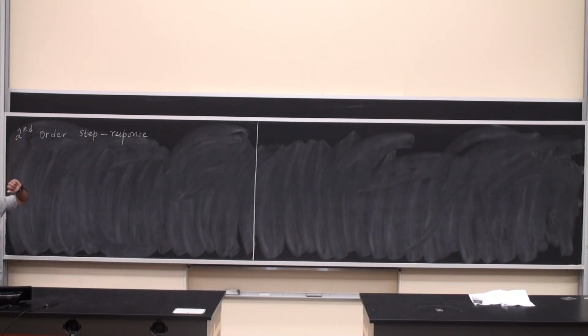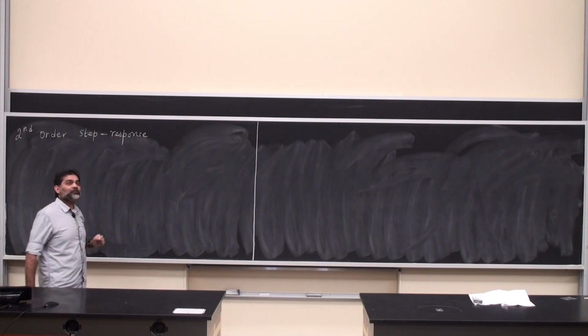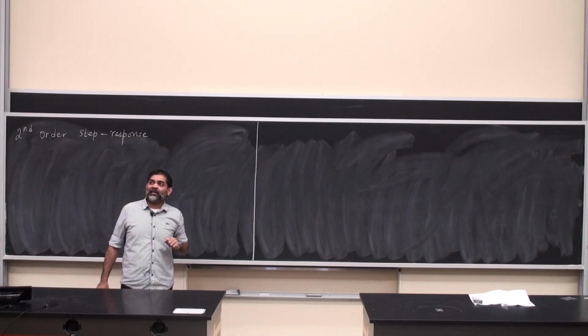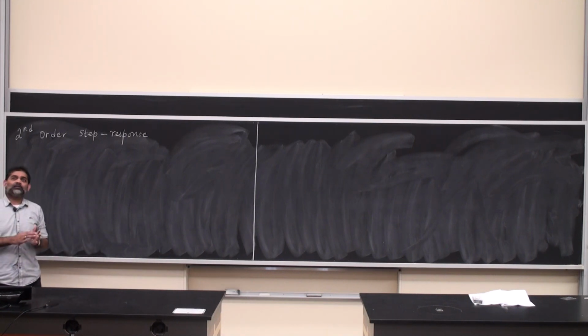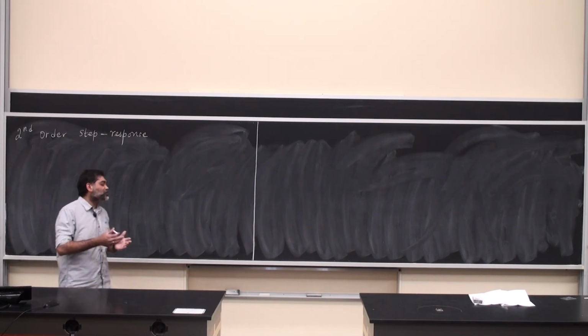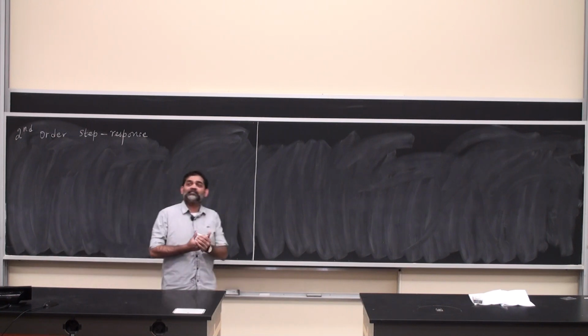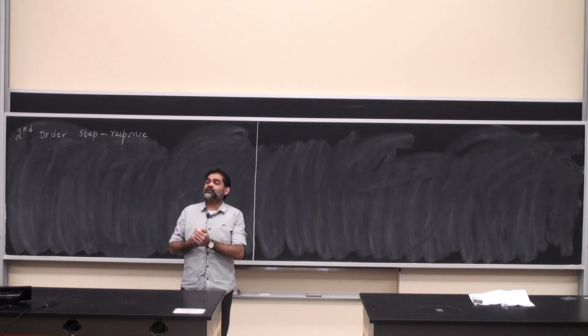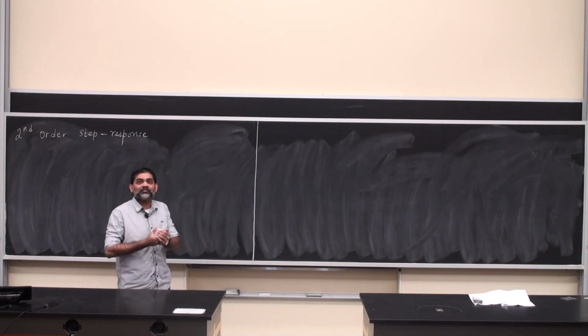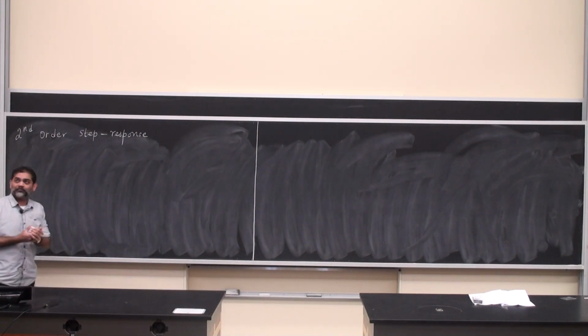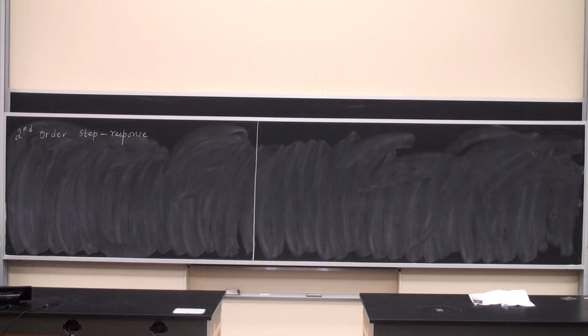This one is the response of a second order system to a step input, has a special meaning because one can perform, hypothetically, experiments on physical bodies which would give us a step response. And using that, one could understand how the system evolves as a function of time. Okay? So this has some special meaning for us.